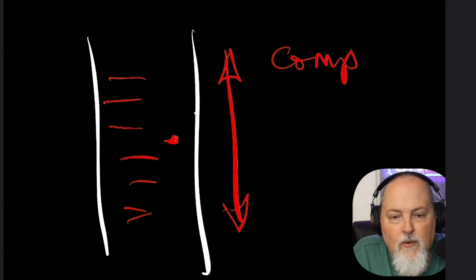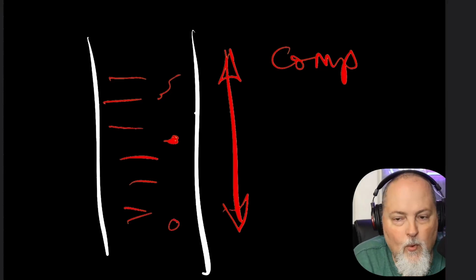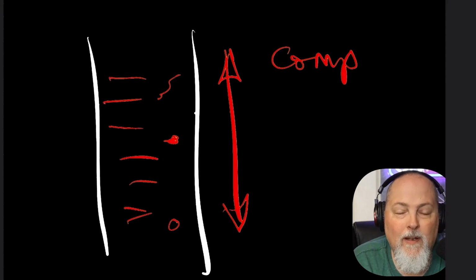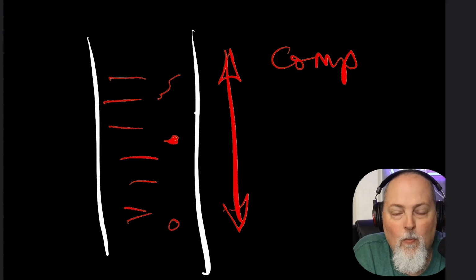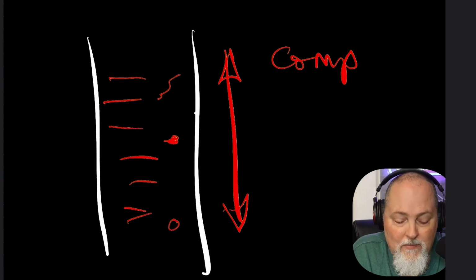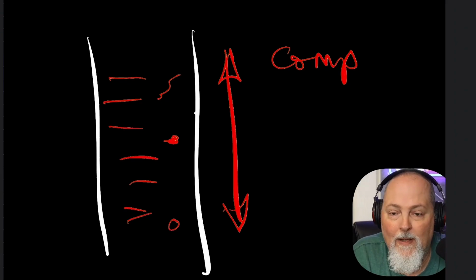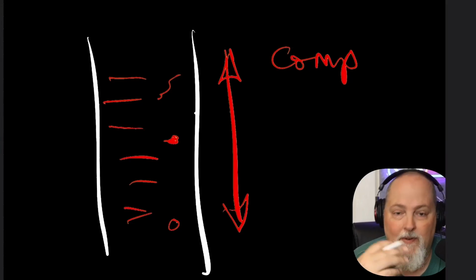Stress concentrations are localized increases in stress caused by cracks, holes. So if I have a little crack in here or a hole, sharp corners, weld defects. This is why welders learn so much about materials and how they behave under temperature changes and how to do good welds, because welders can unintentionally add flaws to the metal that then become problems when we are subjecting the material to these compressive stresses under heat on the outside and the tensile stress on the inside, et cetera, et cetera.